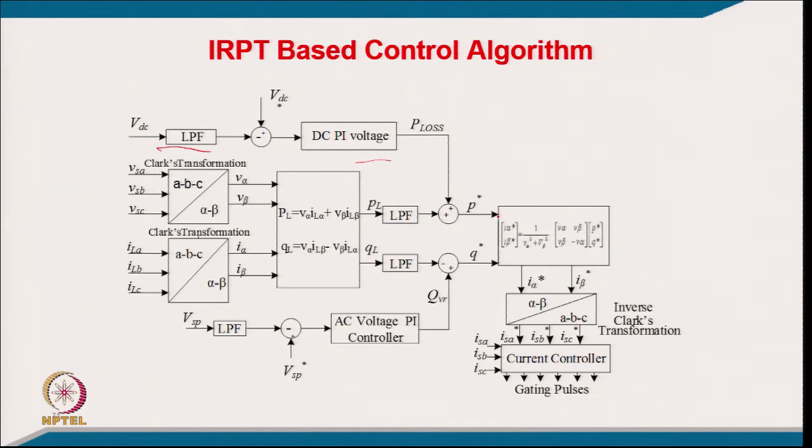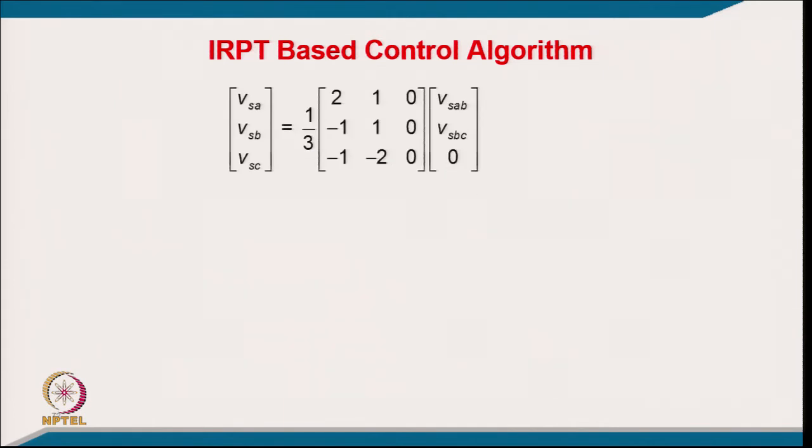So, that is the total active power flowing from the grid towards the system, and of course, for the grid reactive power, this is the total reactive power generated by the shunt active filter minus the load reactive power. Of course, fundamental reactive power has to flow into the grid. So, taking this P and Q by inverse transformation we get I alpha, I beta, and we convert this by inverse Clarke transformation to 3-phase current, the reference grid current. Then we sense the grid current, and we have a current controller for the voltage source converter.